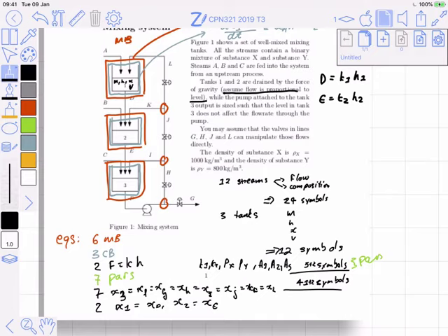Yes. Yes. Now we come to the specifications, right? So I'm going to put that separate because we know that we're going to do input specifications. Okay. So how many input specifications do we have? We have A, B, and C are fully specified streams, which means that they count 2 things each, right? So we have a flow rate and a composition, right, for each one of those things. So we've got 2 there, 2 there, 2 there.